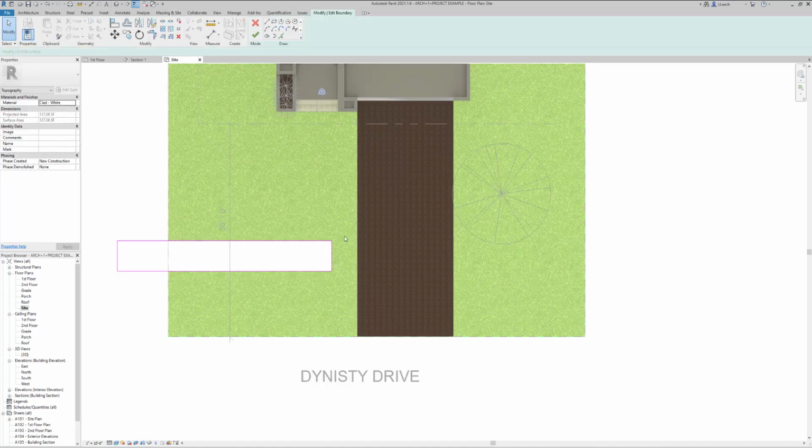So now I'm going to click on my sidewalk here. I'm going to go back to edit boundary, and I could drag this all the way across maybe. Let me do that. Now I'm going to drag this one to the edge too. So what I need to do is, again, it can't overlap. So I'm going to see if it lets me cut out here, maybe here. I just basically have to split that line into 3 pieces. So I click this, delete it, click this, hit delete.